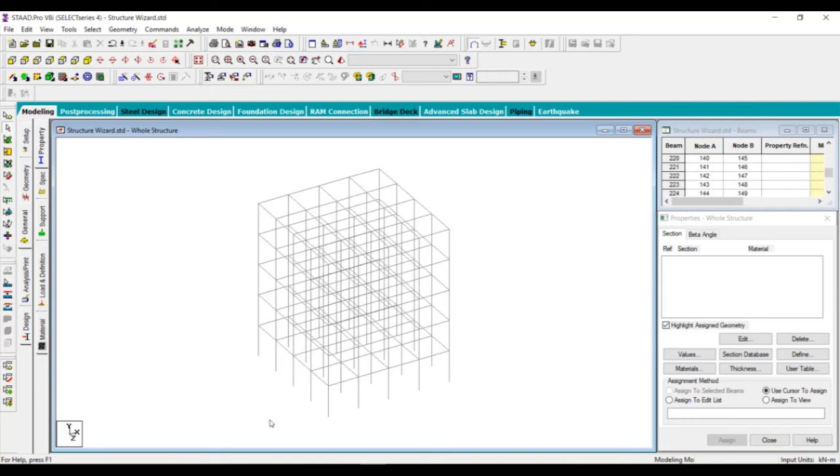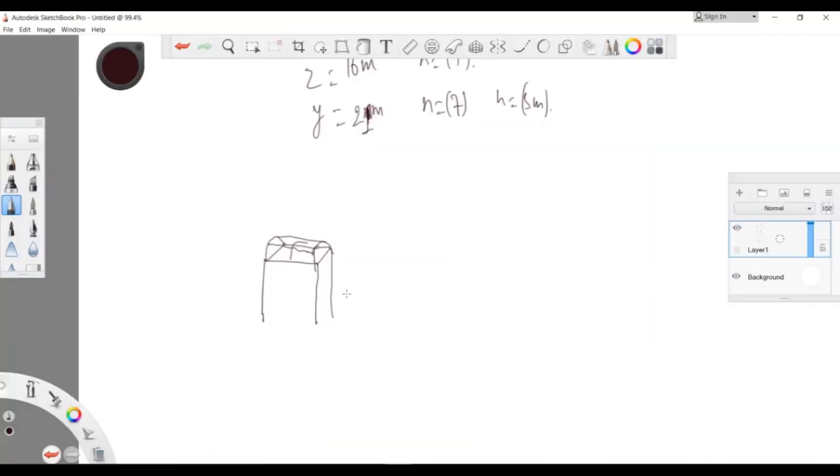For that, you have to remember that if this is your frame, and suppose that this is the front view of the frame, then you make sure that the vertical members that you got of the truss lie perfectly on the columns, so that the load is transferred accurately to the columns and the beam doesn't take much of the load.